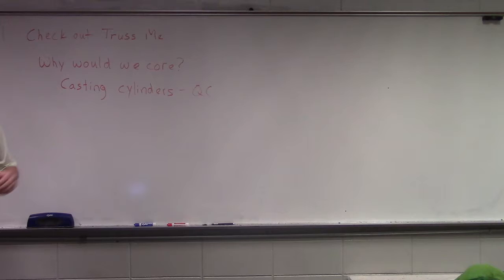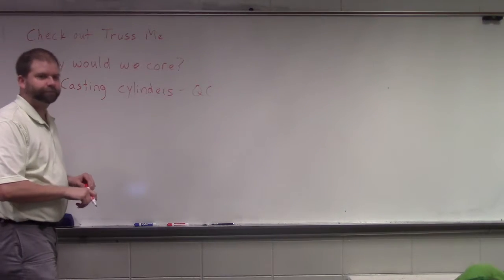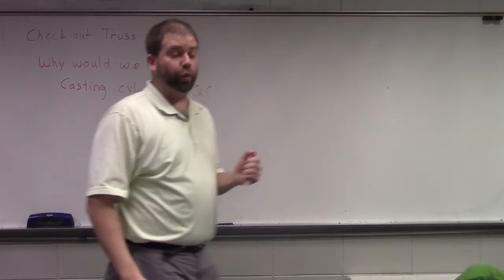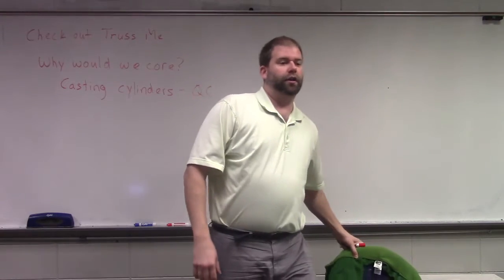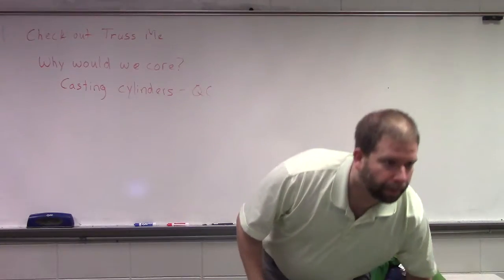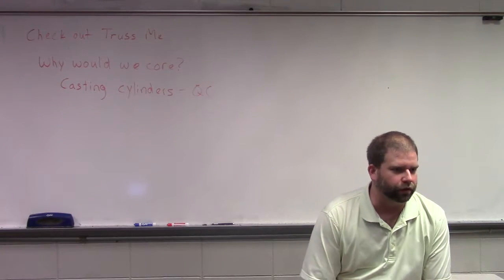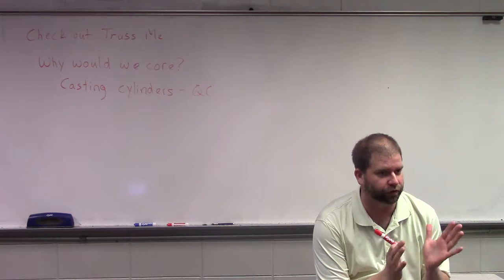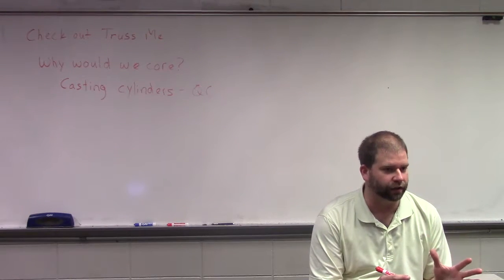So you're talking about the test strength that was done in the lab or out? Correct. So then the casting cylinders are out in the field, correct? So we can do field cures and we can do lab cured cylinders. Wouldn't the whole point be to do a field cure? Not necessarily, because we're not interested in trying to determine what the strength of the members in the structure is. Think about how big a cylinder is.